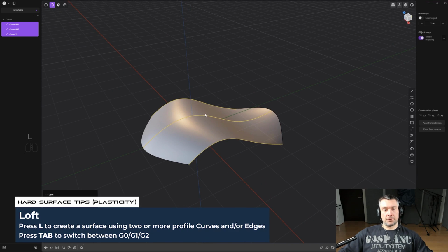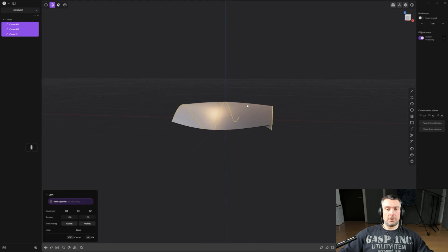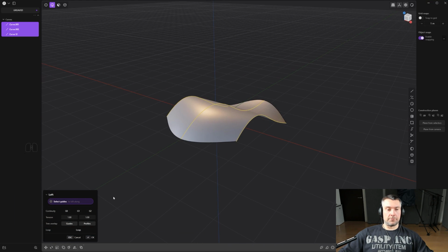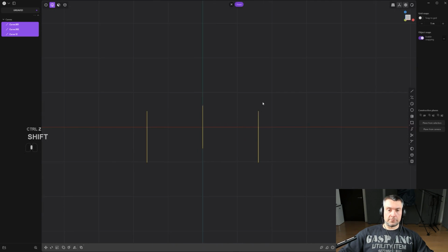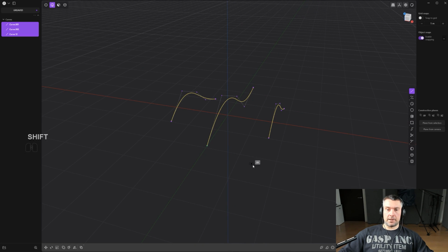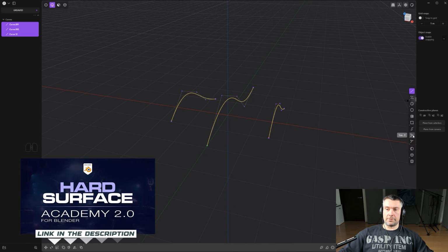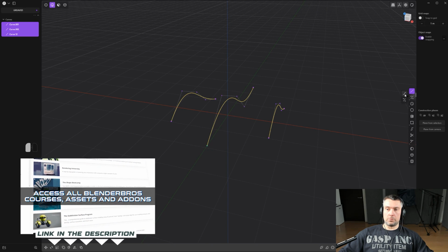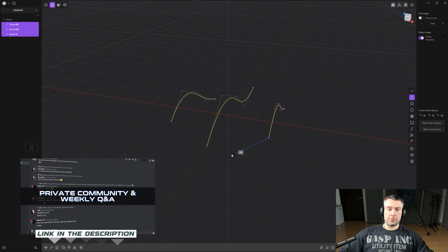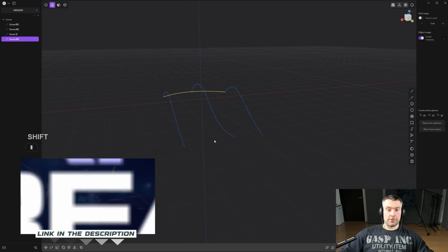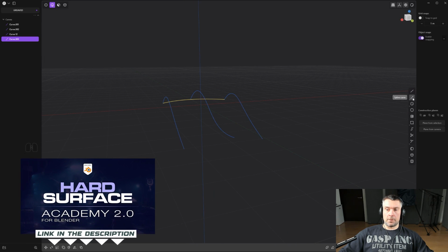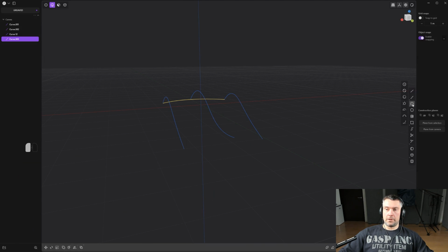Now, what you can do in addition to that, you can define the curvature or the profile of this loft, right? So you see that it says select the guides. We don't have any guides, but we're going to create them. So what we're going to do is grab this curve, and maybe with this one. So hold and click on this spline curve, and we're going to combine all of these together like that, and right click. And in the back, we're going to do something different, okay? So we're going to grab, let's say, this circle, hold, and we're going to go to 3-point circle, and we're going to click once, twice, and thrice, and do that.